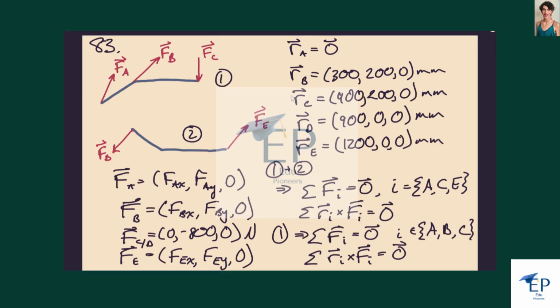And then we have our reaction forces. So here's the reaction force where the upper bar is pinned to ground. Here's the internal force between the two linkages. The external load, which is acting at C in this case. In the next problem, it's going to be acting on D. And then the other reaction force over here at point E.